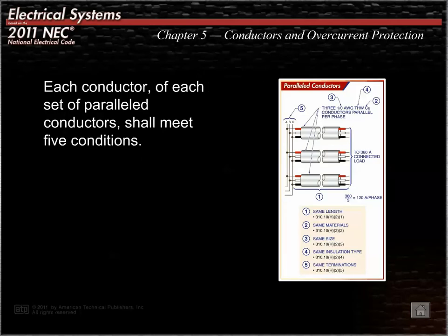Parallel conductors are two or more conductors that are electrically connected at both ends to form a single conductor. Despite the wide range of conductor sizes available, there may be installations in which it is desirable to use parallel conductors to meet a specific design consideration or installation requirement. See Article 310.10(H)(1) through (6) for specific rules concerning the installation of parallel conductors.